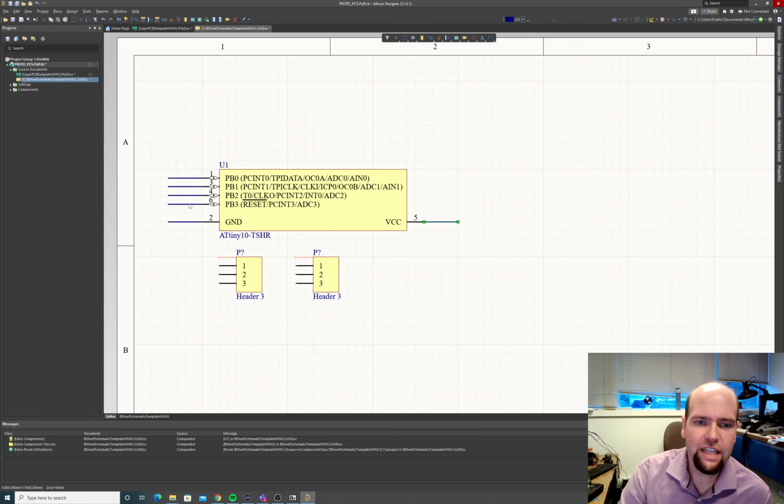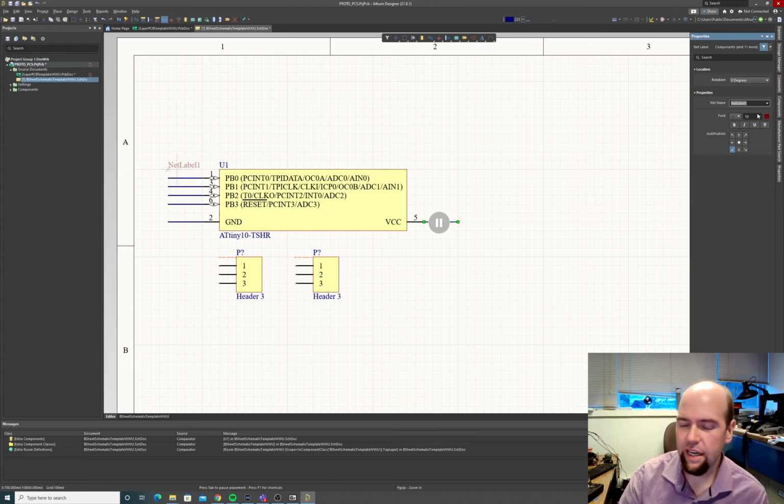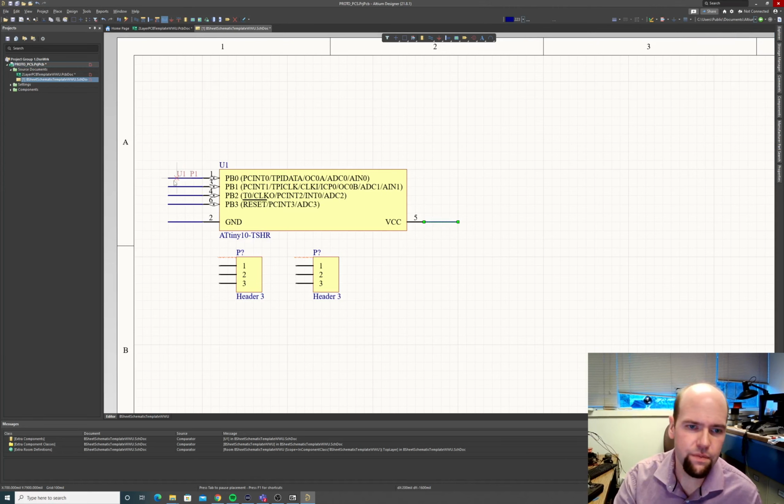And I'm now going to label each one of these. To make sure we don't have duplicate labels on our design, this is part U1. It's already been annotated. I hit tab to go over to that. I'm just going to label this signal U1 P1. I'm going to drop that there. And now it automatically advanced to U1 P2. That's kind of nice. So we're going to have to make sure we go to pin 2, right?